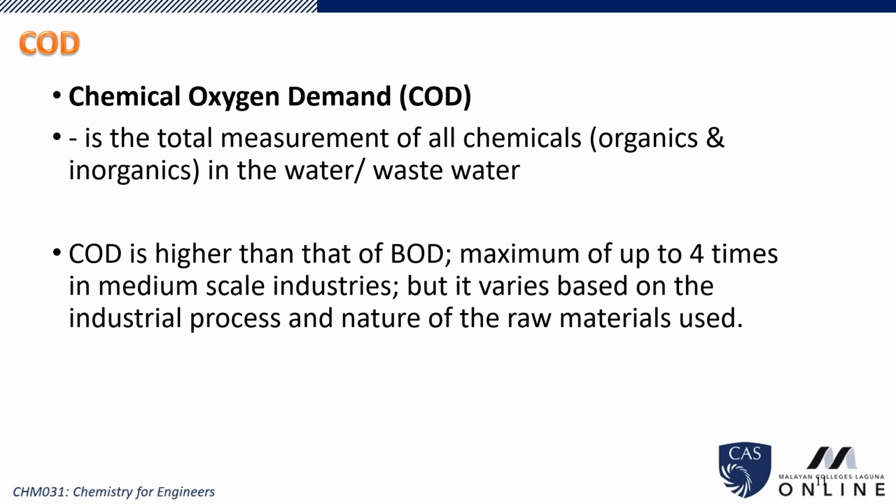Chemical oxygen demand measures the total oxygen required to oxidize all substances, including both organic and inorganic components. COD is usually higher than BOD because it includes all oxidizable substances. Industries often monitor chemical oxygen demand, while municipalities focus on biological oxygen demand.